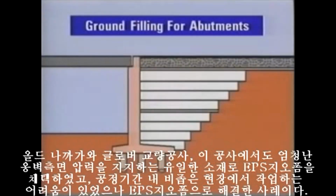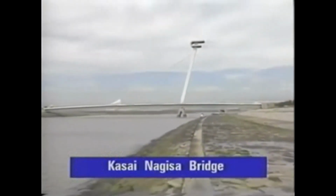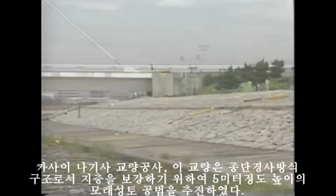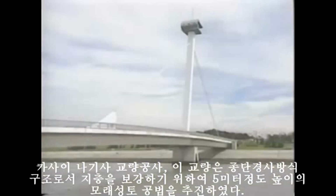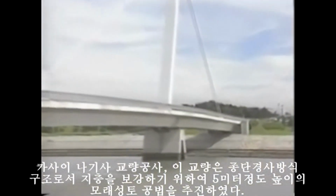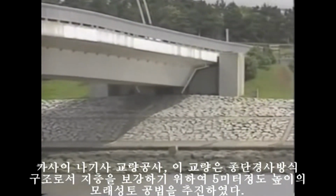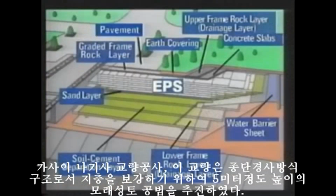The Kasi Nagisa Bridge is an incline bridge, connecting the Kasi Beach and the seaside park. The abutment backing of the bridge required about 15 feet of ground fill. There was concern that the weight of conventional sand fill would cause ground settlement and negatively affect the structure. Therefore, the EPS construction method was employed because of its lightweight characteristics, rapid construction time, and overall project savings.